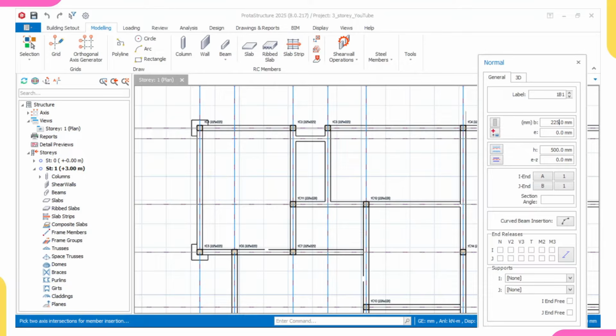Then what is my beam depth? The depth I'll be using in this structure is 450. Remember, the minimum depth that you can use is 300. Safety and economy are our priority. So I'll first of all go with the minimum because of safety, which is 300. Then if it fails during design, I can increase it. But if it doesn't fail, that means it's okay.